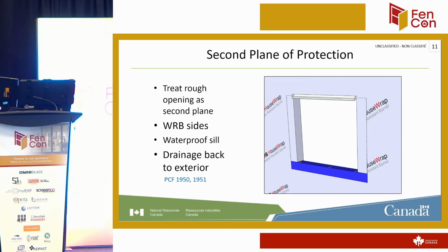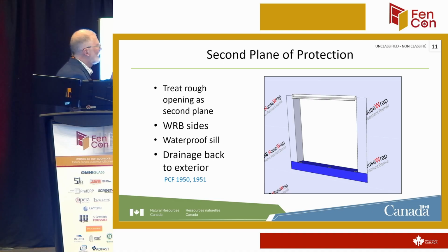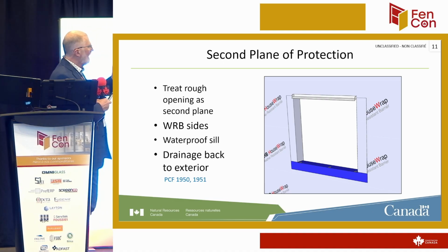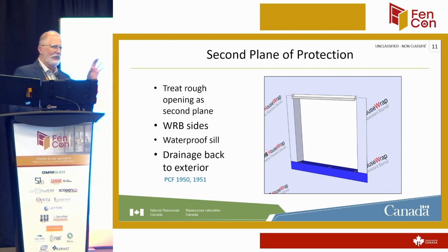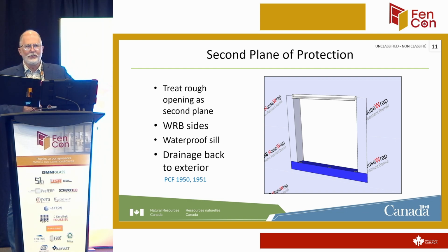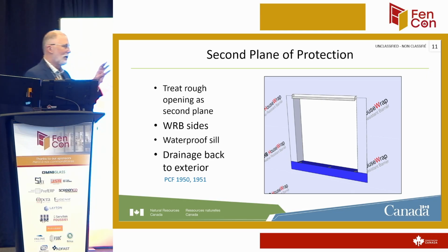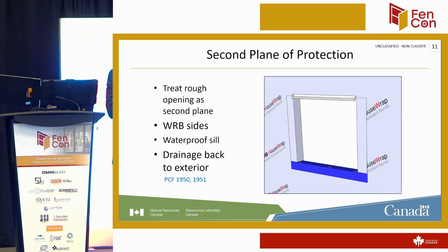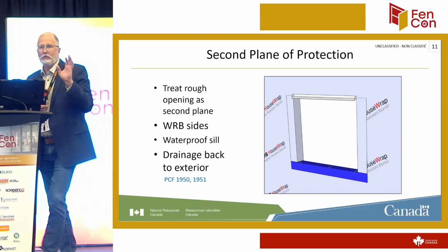All right. So here's where the change is happening in the building code. And really, it's all about common sense. If water gets in there, there's just moisture-sensitive materials that need to be protected. So now that you've got this application where you've got that sill pan, even if you don't do the sides, you've got gravity as your friend, right?